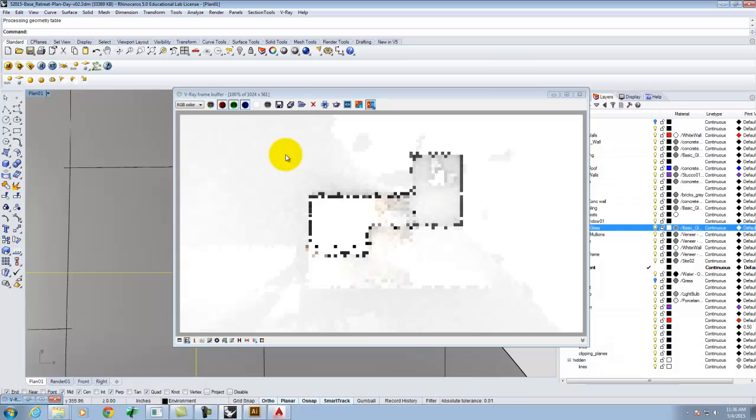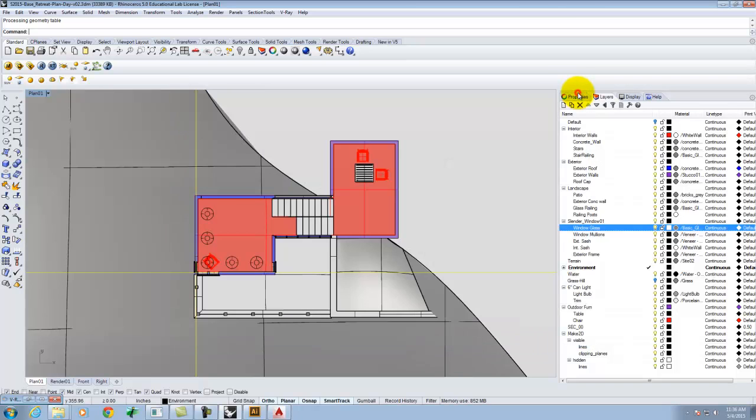And this time we're going to have more accurate sunlight. Now the problem was I turned the sun off when I did this. And herein lies one of the biggest challenges with doing these kinds of clay renderings: if you turn the sun back on, the sun's going to be really, really bright against this white background. And so what I've done to improve what this looks like is I've actually gone and created another sun, or I will create another sun, but I'm going to use a basic directional light instead of the sun. So let me go ahead and turn the sun on for a second.